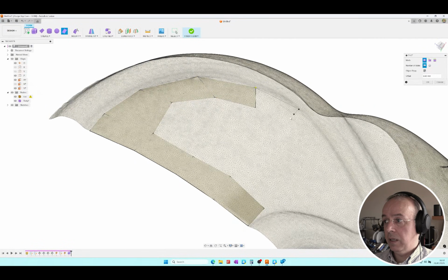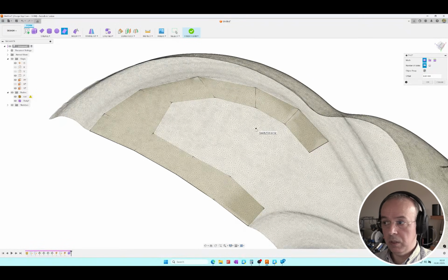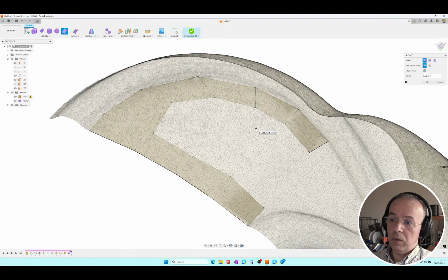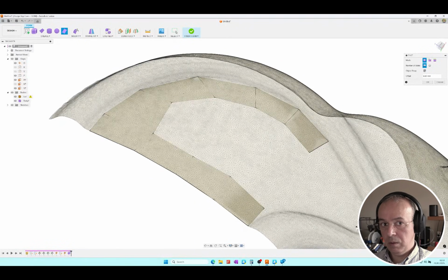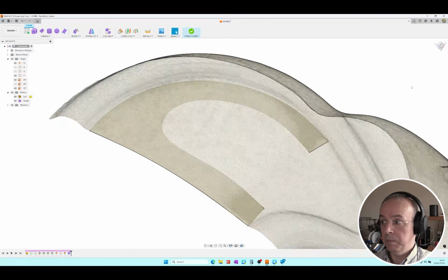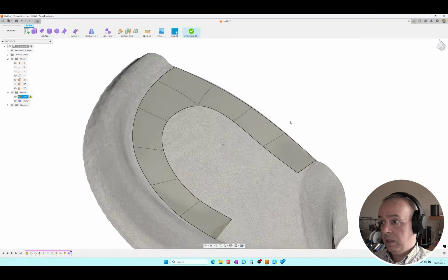The main question here, which often requires attention and adjustments, is what size should the polygons be? Should they be larger or smaller? This depends on the complexity of the area you're working on. If it's a very intricate area, it's best to use smaller polygons. For less intricate areas, larger polygons are fine. I'll consider this done for now and will accept it as is.